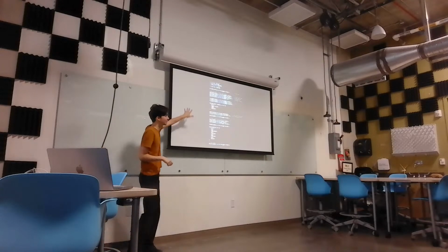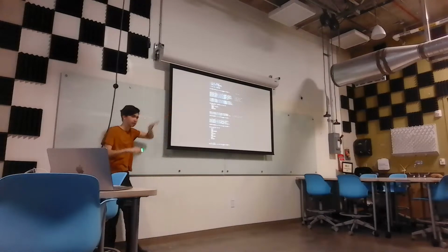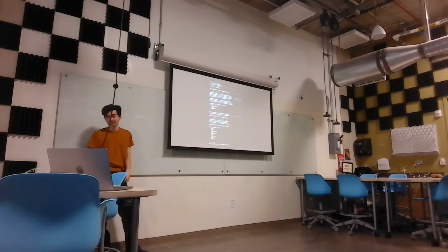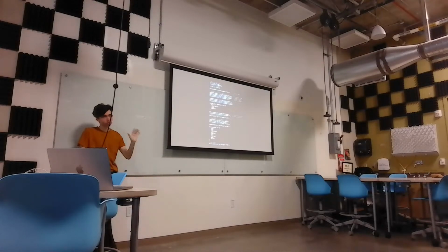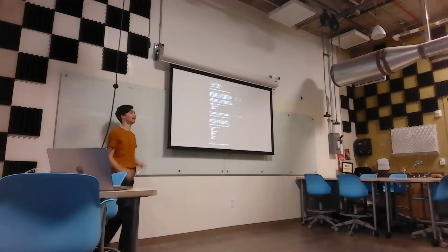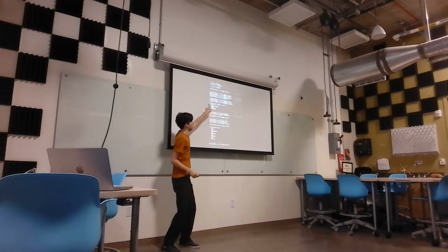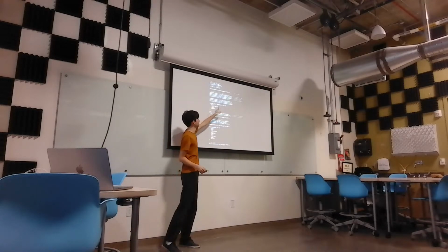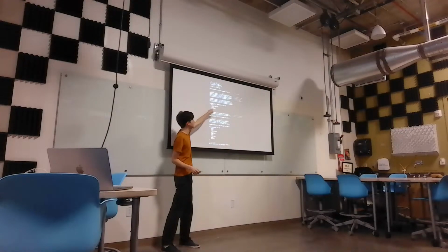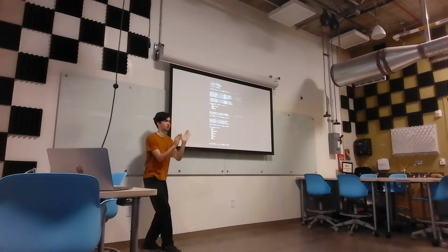This is crazy. I manually looked at the datasheet. The ST datasheet is like, okay, you gotta enable these 20 things, then set up the thing, and then finally enable the thing. And then it'll go. This took me forever to figure out. All these lines are saying, in this region of memory, put in some bit. These names refer to bits in certain positions.